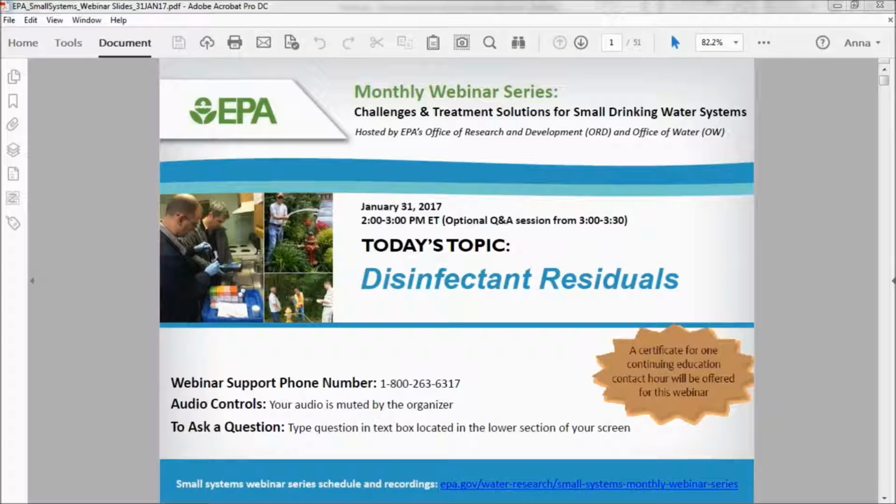There's always a trade-off between how much chlorine residual a utility carries and how much disinfection byproducts are formed. Drinking water treatment is balancing multiple risks: risks from microbial pathogens and risks of disinfection byproducts. And they're both very important, but we have to assess both of them. And I certainly think, with what we know today about the nature of microbial pathogens and Legionella, that we definitely need to provide continuous disinfection residual.